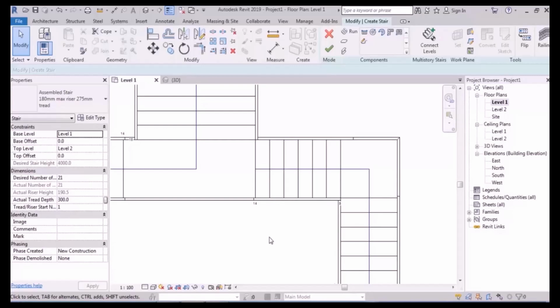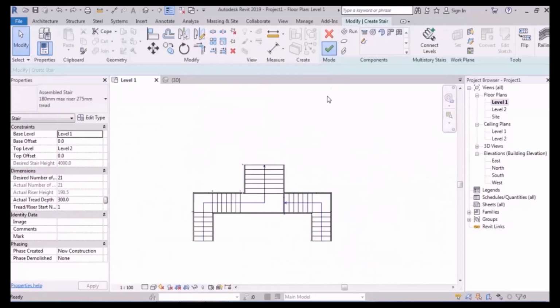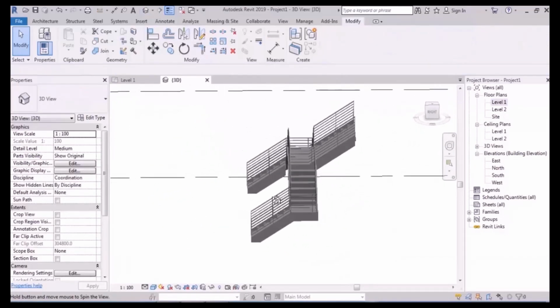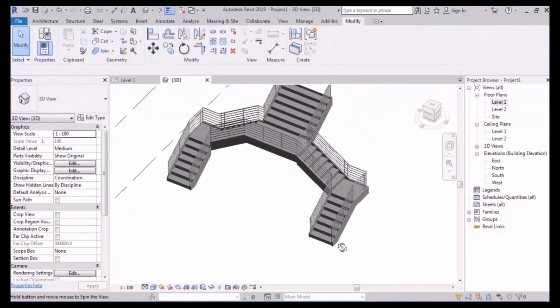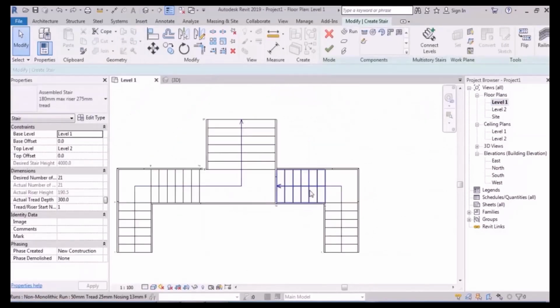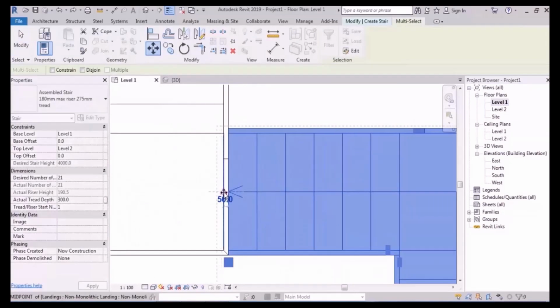Number 3, the railings after finishing. If it's wrong and you click on finish, you can find this out really easily in the 3D, just like this. The railings block this path, so it's wrong. But if they're connected, everything is alright.